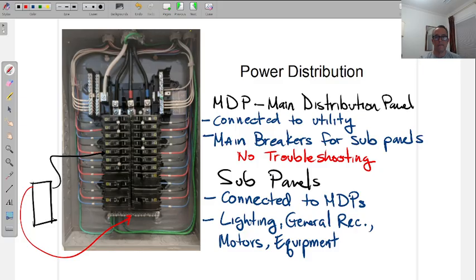You have it opposite, right? Like the red cable goes to that red cable? It doesn't matter with AC voltage. With DC voltage, it does, because that's what it's indicating, positive and negative. So for DC, I would put the red on positive and the black on negative. But for AC voltage, it doesn't matter. Okay, good. These are all important questions, so anytime you're thinking of stuff like that, ask them. They're good.